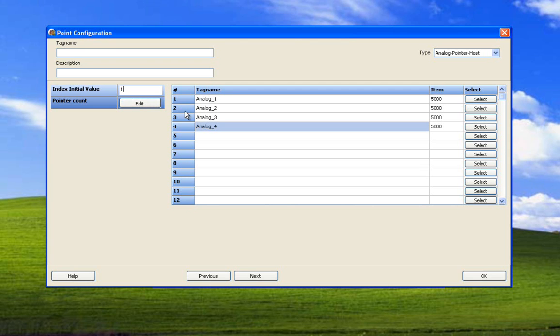So you create a button, for example, to open the window that shows the fire pump, and as one of the button commands you set this tag name's index value to 2, and then when the screen opens and you have the animation that is looking at the pump pressure, it will look at this tag for its animation. If you set it for 3, it'll look at this tag for its animation. So this is a pointer to an actual tag. That's really all this is. It's just a way to not have to duplicate graphics for things that are identical on screens.